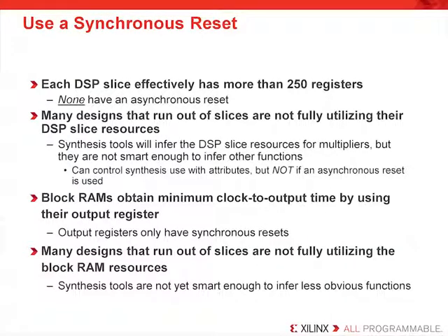It is important to remember that the DSP slice and block RAM resources only use a synchronous reset, so if you code for an asynchronous behavior, your synthesis tool will not be able to infer the DSP slice or the block RAM. Now this will hurt your performance and increase your power consumption significantly. Taking advantage of the dedicated hardware resources like this is going to provide extra slice resources, which will also give the tools the ability to reach a higher design speed as well.